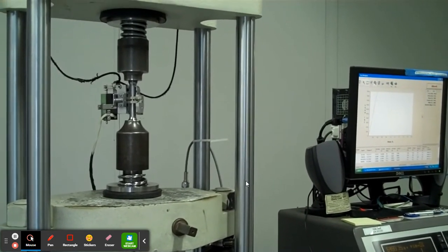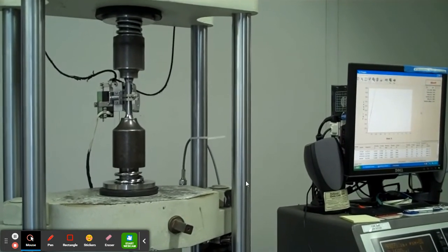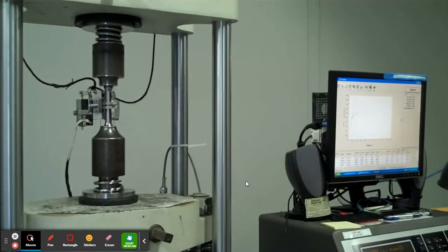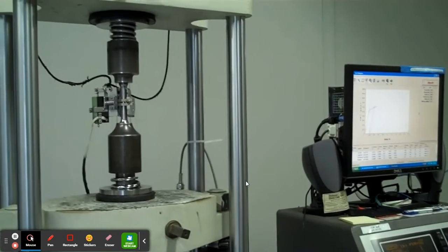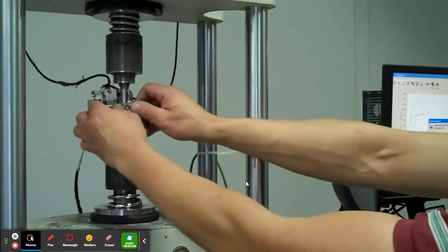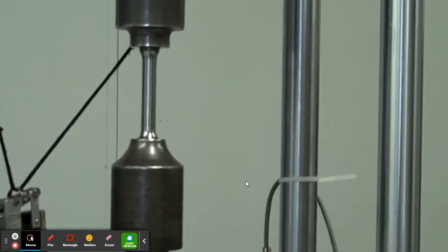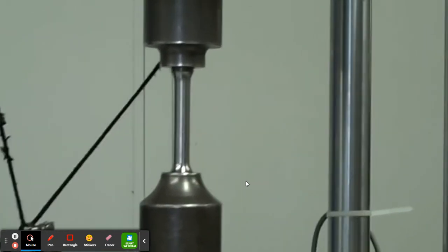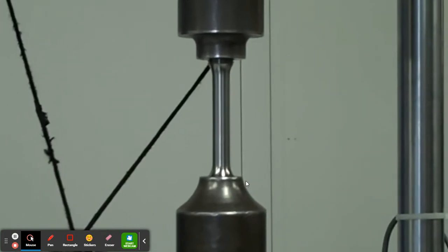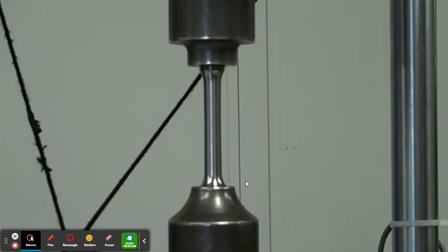And primarily, you're going to look at that screen that's to the right. Kind of hard to watch both things, but what they're doing, they're getting a yield strength right now with that test reading. But that's not the actual test that they do on it. After yield strength has been determined, remove extensometer and continue test to failure. So now they start to pull it apart. Okay? Not real exciting right here. It's kind of like watching paint dry, but that's what it is.